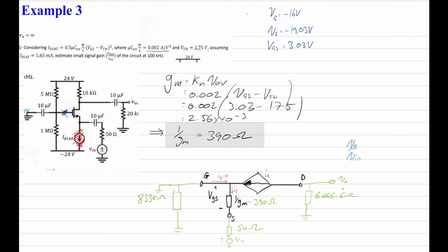Well, it's usually easier to start from the output voltage and deal with that first. So we can immediately say that V out, V equals IR, and the current over here is actually flowing away from the ground, which is opposite to where it normally goes. And we know that because of the direction of the arrow of the current over here. So it's actually flowing like that. Normally, current will flow towards the ground.